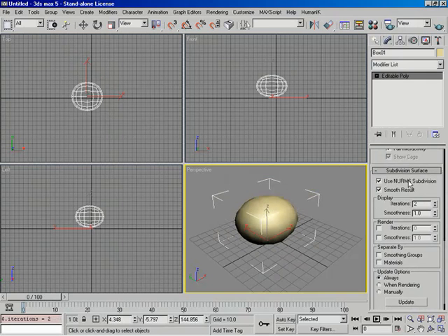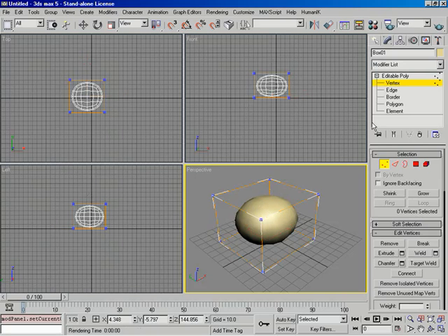And now, what is NURMS? NURMS stands for Non-Uniform Rational Mesh Smooth. Basically, it's like I'm using a Mesh Smooth modifier on top of my editable poly. What's really cool, though, is this is all built into the poly itself. I can come up here to editable poly, expand it, and select one of my sub-objects and check it out. I get my low-res cage that I can now manipulate, and the manipulations that I apply to it are going to translate over to the high-res geometry.